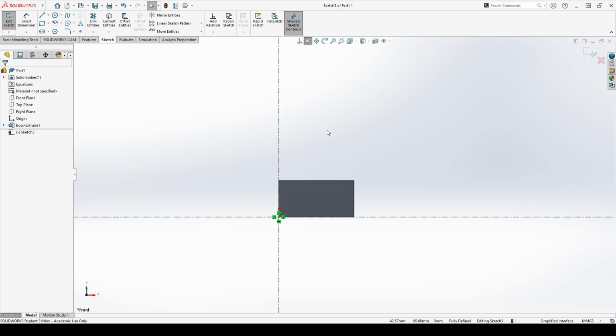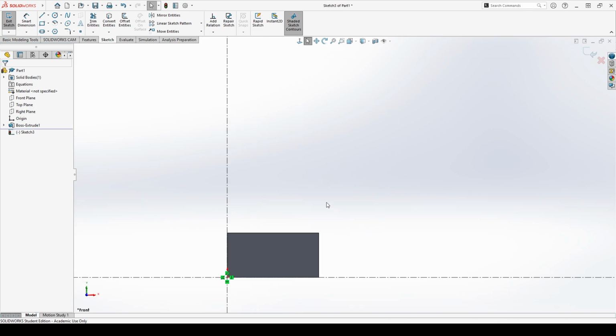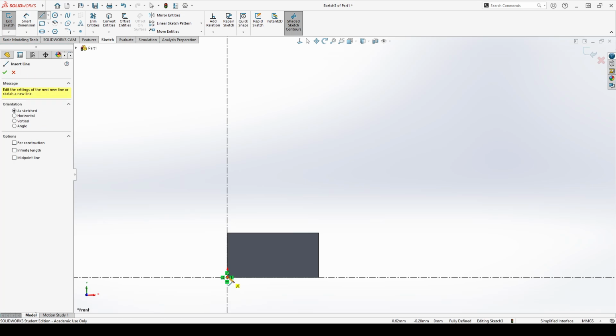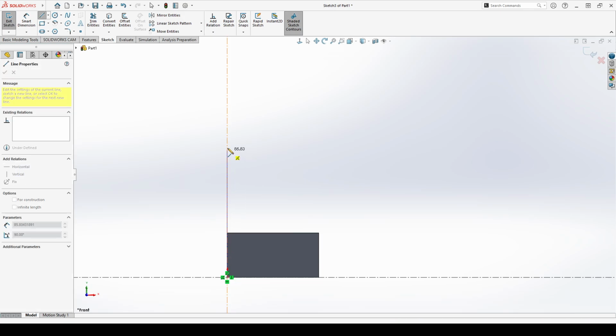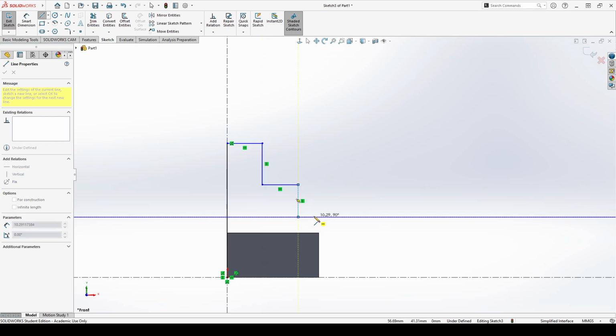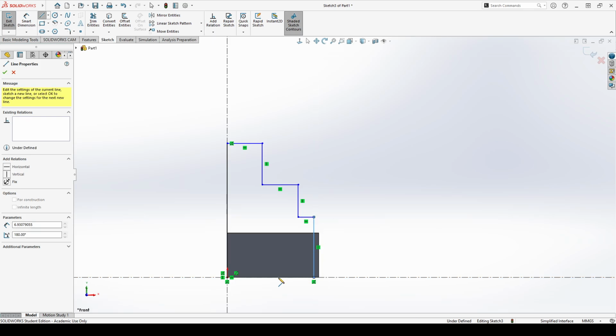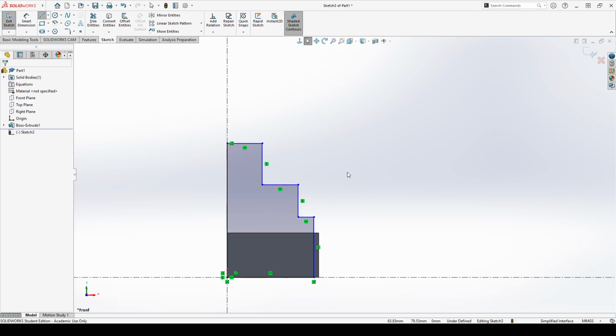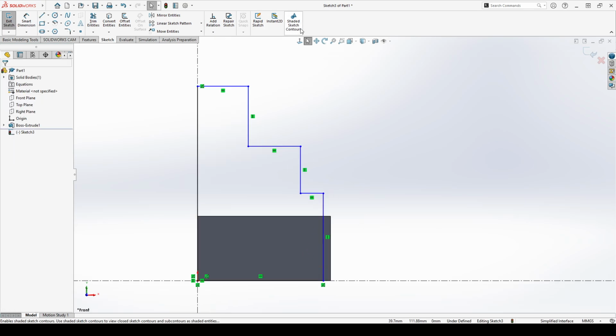You know they're the same width, so you can make that in one sketch. You can either start from here, or you can start from the top. It's all up to you. I'm going to make it as simple as possible, so we're going to start from the origin. We're going to go up, make the profile casually, like so, and pull it all the way down and complete the sketch. It's colored now. You can uncheck this, and now it's all confusing, but if you check that, you know your sketch is closed.